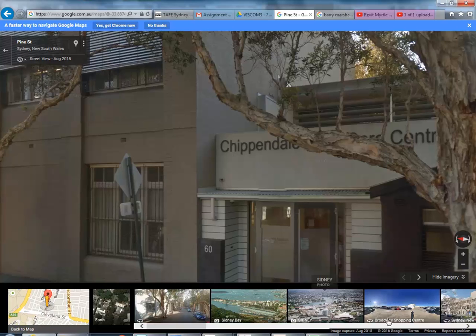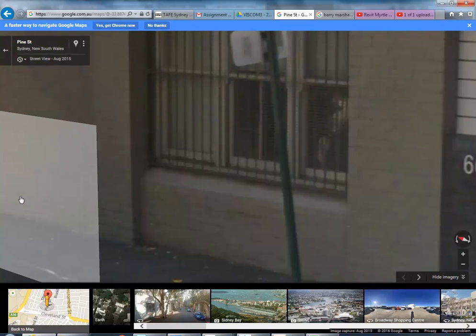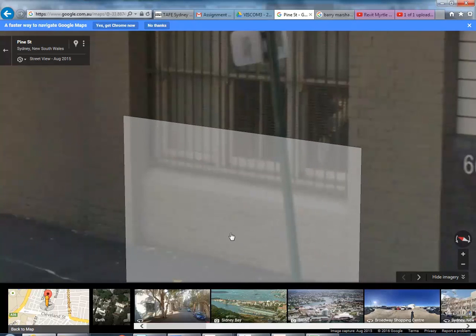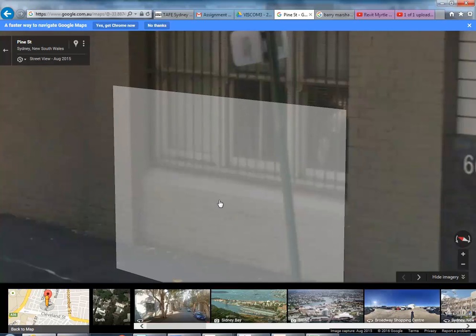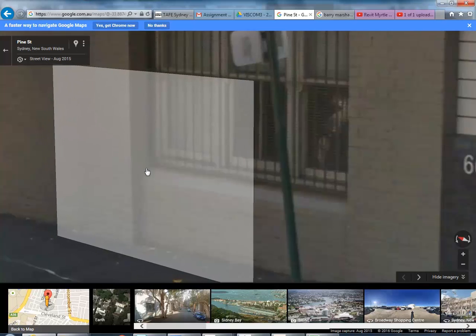And let's just have a look at Street View. And so you know about counting bricks. If you have a photo where you can see bricks, you can try counting them. So 1, 2, 3, 4, 5, 6, 7, 8, 9, 10, let's say 10 courses. And so do you know how high a course is? 80, close, not far off 80, it's 86 or 85.